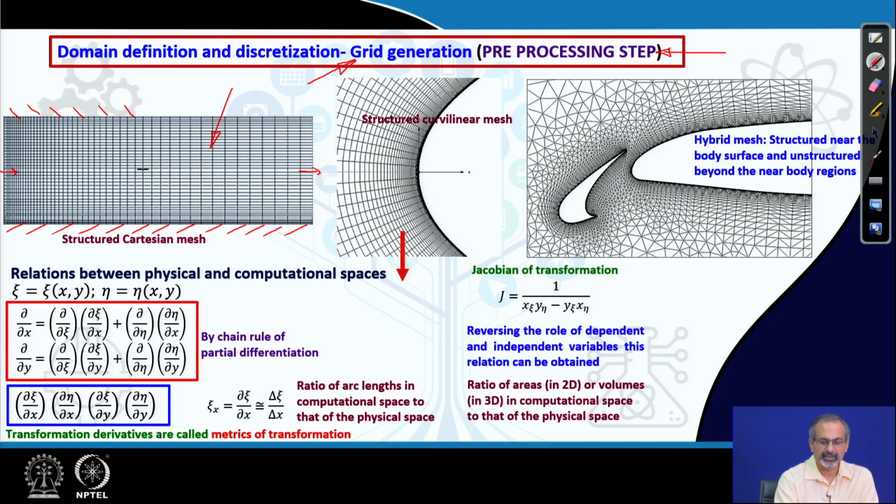But before you do all that, as you can see, we have discretized the domain into a large number of rectangular control volumes, if you look at it from the control volume point of view. Or you can also look at it as a large number of grid points. If you look at one of the intersection points, then that happens to be a grid point.